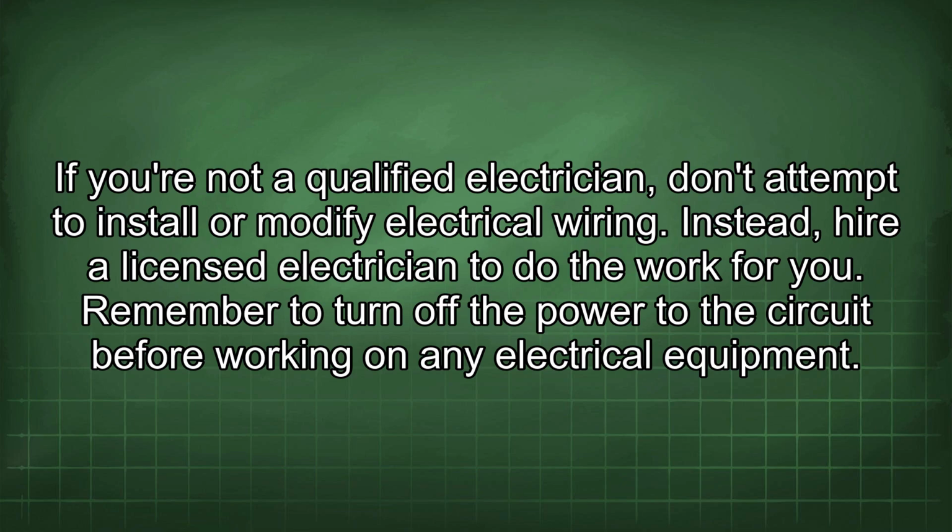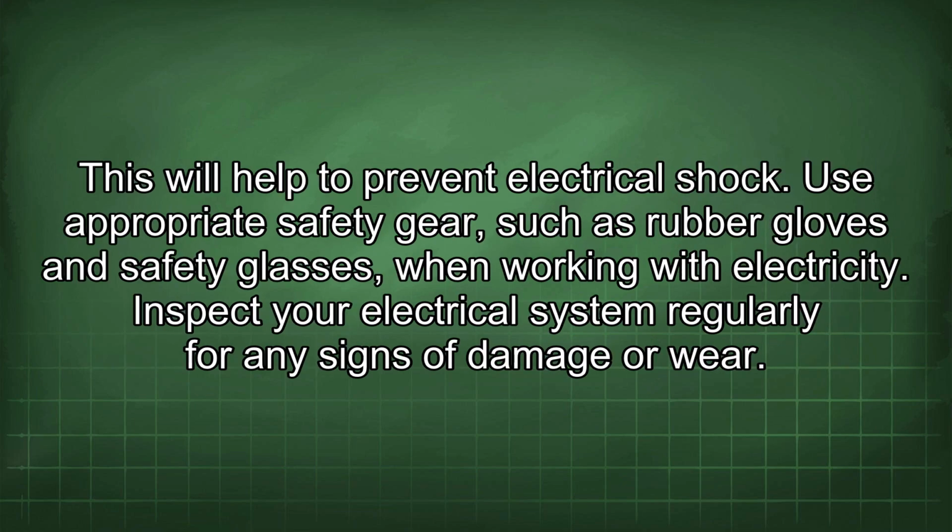Remember to turn off the power to the circuit before working on any electrical equipment. This will help to prevent electrical shock. Use appropriate safety gear such as rubber gloves and safety glasses when working with electricity.